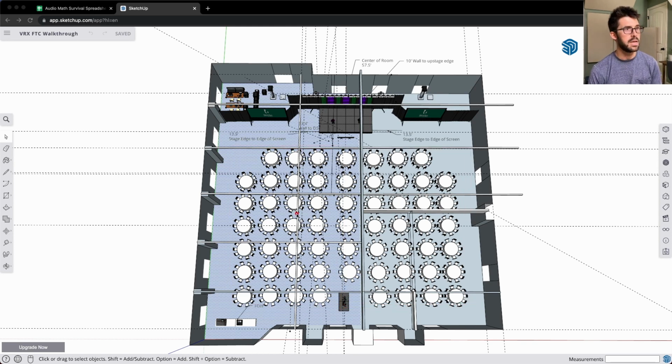It is this beam right here that I'm going to be hanging my PA off of. Well, it's going to have a 40-foot stick of truss, so that determines my maximum width of the two arrays between each other. And I know that it is also 12 feet downstage. And so that is going to determine the x-axis, or the point in the room in which the PA is hung off of. And we already talked about I have a maximum trim height of 18 feet. I have truss there, and so it's going to be under it. So best case scenario is 16.5 feet.